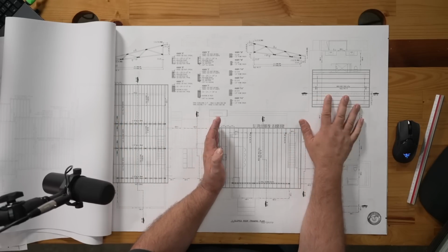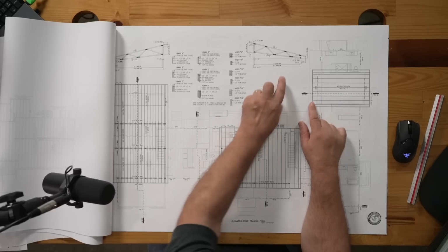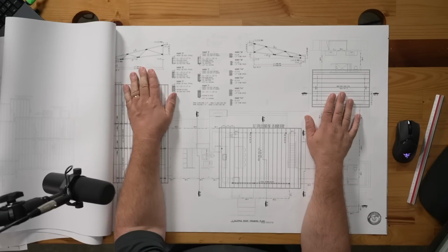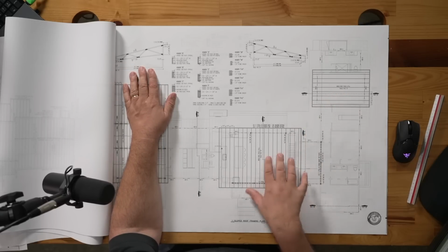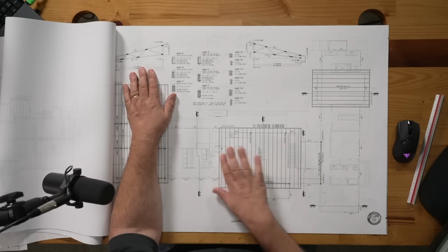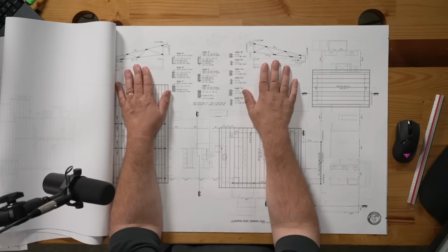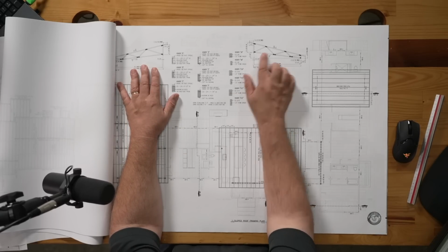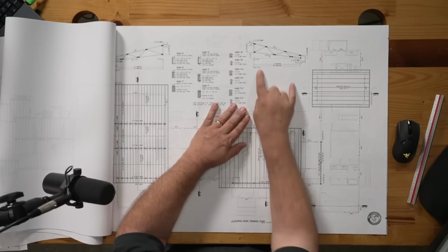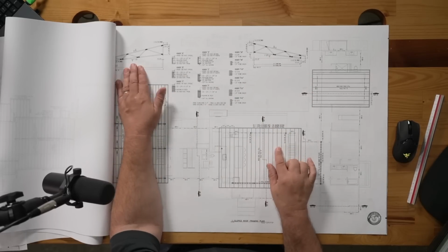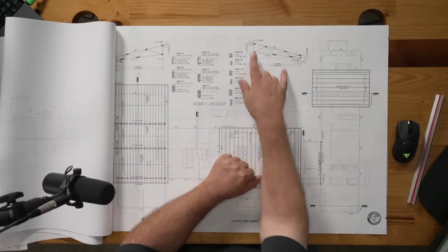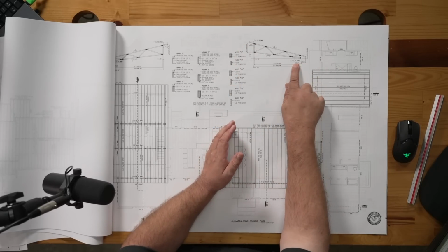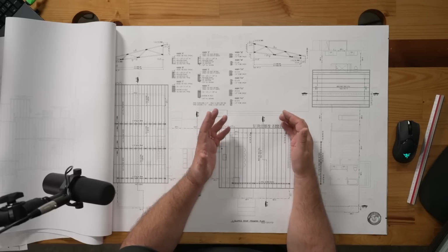These two roofs are going to be trussed roofs, and you can see that I drew the truss profile here for that roof and the truss profile B here for this roof, truss type B. Basically what I'm showing there is my intent on the truss profile. What are the slopes? What does that look like? These are both going to have interior slopes, and then we'll have some space for insulation. And what are the overhangs? What is it getting cut back to, trimmed back to for the framer?